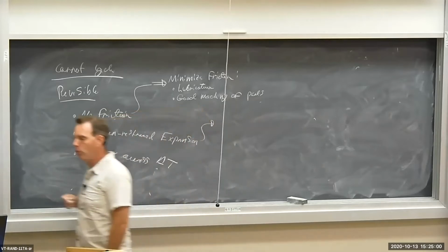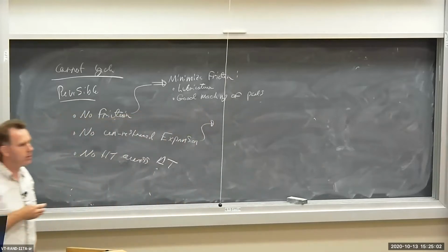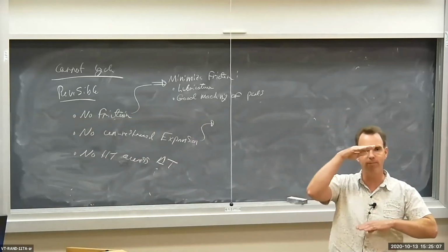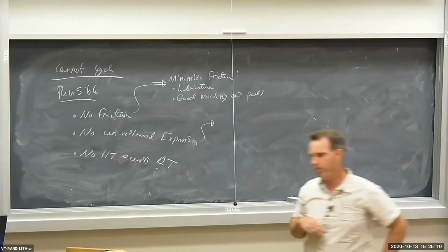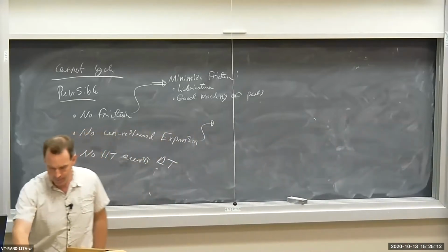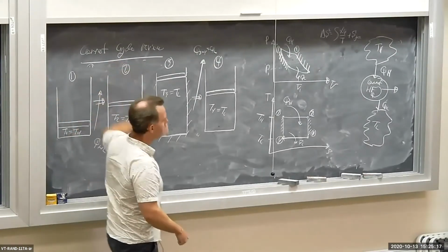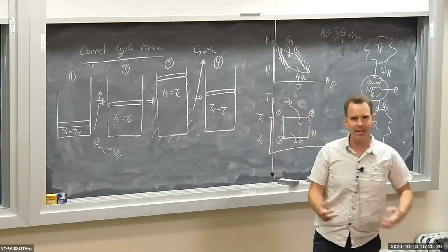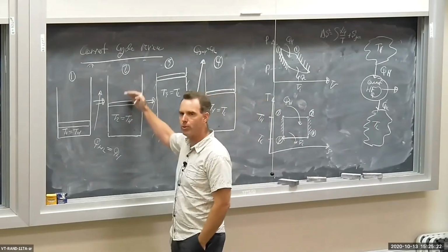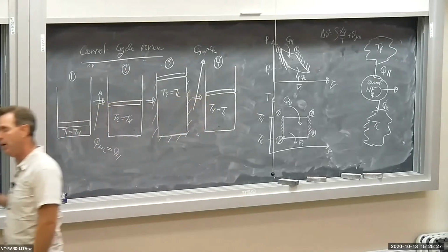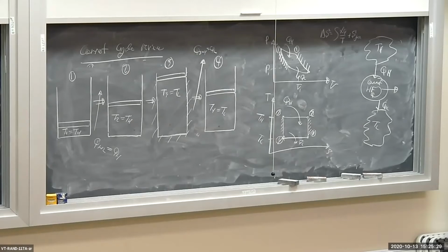Well, we can minimize the presence of unrestrained expansion by having the piston cylinder device work very slowly. Remember, unrestrained expansion is caused by the piston jerking up and down so quickly that the gas doesn't have a chance to move along with the piston, forming a low pressure or perhaps a partial vacuum near the piston. Remember, unrestrained expansion is irreversible, so we want the piston to move slowly.